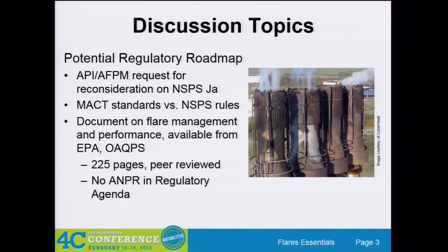And I hope this isn't your flare, but having flares next to each other is a very bad idea. Just because one needs maintenance, you can't do maintenance on one without all of them going down. So generally, some people say they can save money by putting them all in the same support structure, but it's generally not a good idea.